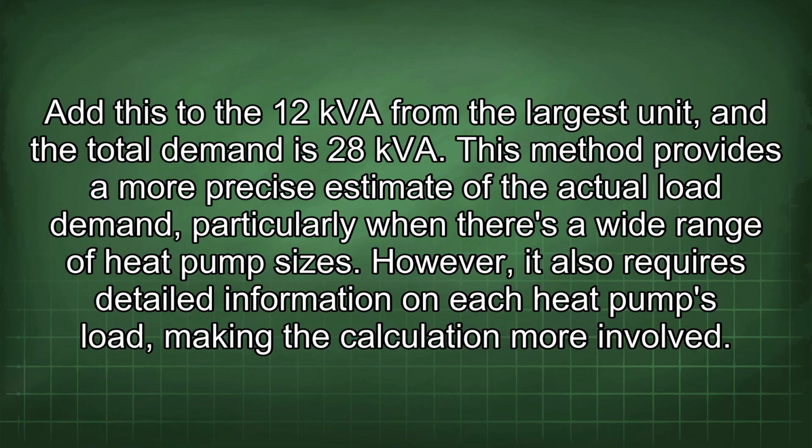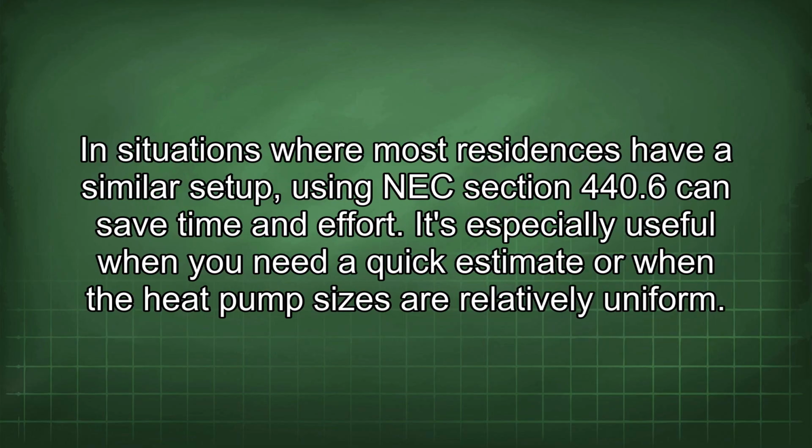This method provides a more precise estimate of the actual load demand, particularly when there's a wide range of heat pump sizes. However, it also requires detailed information on each heat pump's load, making the calculation more involved. In situations where most residences have a similar setup, using NEC section 440.6 can save time and effort. It's especially useful when you need a quick estimate or when the heat pump sizes are relatively uniform.